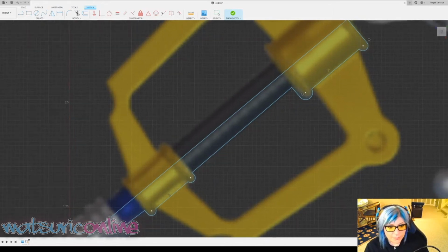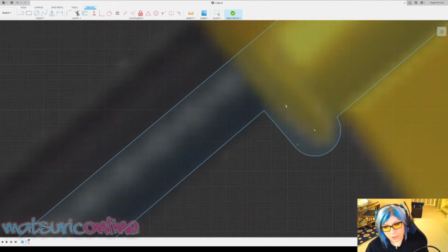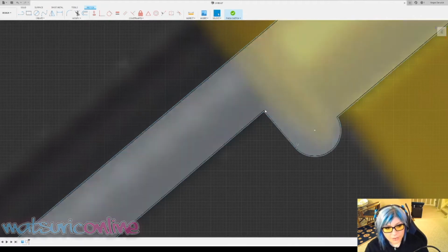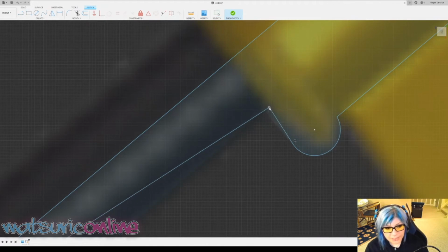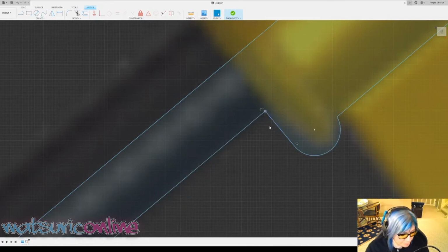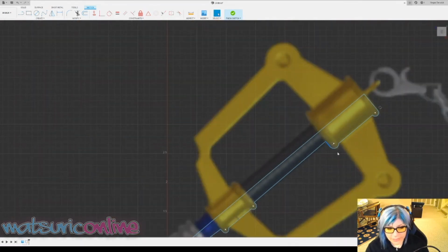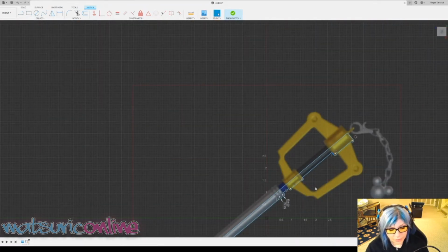So I mentioned that I kind of messed up, but what I'm going to do is show you the push-pull function. You can either press push-pull, or you can take this line and move it. Unfortunately, it moves all of my lines with this one. So I'm going to undo that, and I want to move this whole line inwards. Okay, and it gives it just an ever so slightly different look.